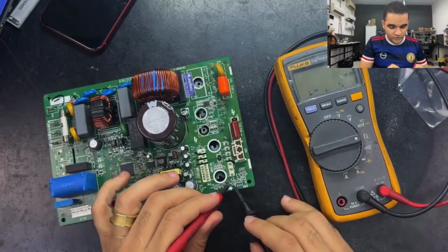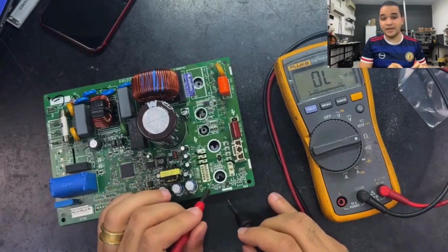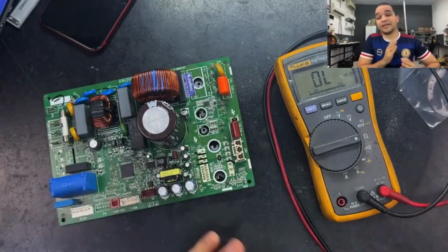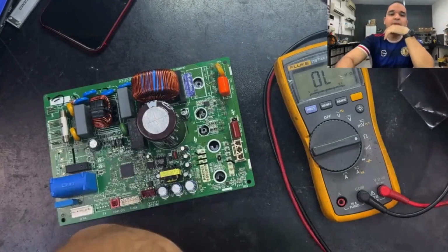So here's the path. I will follow the traces, measure each resistor, and measure the pins of the comparator to see how much voltage each pin has, to see if this voltage logic makes sense. And then, if everything is okay, or if I find any interference in this circuit, I will find the defect in the board. Basically, we analyze two circuits with the interpretation of the error code, and I only replace the faulty component.